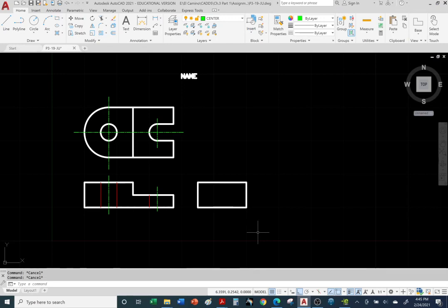Once you complete your drawing, wait till the very end to change your line type scale. It'll change the spacing between the gaps on your center lines and your red hidden lines. So I'm going to go here in the command line and click inside. It's waiting for me to type something in. I'm going to type in LT scale or just LT, and you can see it's already giving me an option. Oh, you want LT scale. I can type in LTS, enter, or I can select from here. Okay, so pick it. It's telling me, hey, you want to change your LTS.